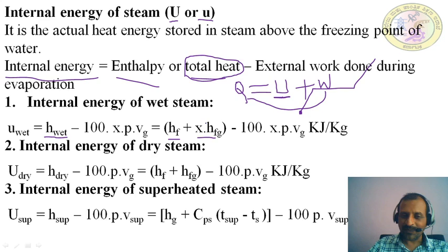And constant volume lines. There are some constant volume lines also shown here. And next is constant pressure lines. See here shown P 50 bar, P 10 bar, then 5 bar, then 1 bar, then 0.1 bar, right? So these are all the constant pressures shown here. Then next similarly there are isothermal lines, isentropic lines, throttling lines, right? But in this drawing only 3 lines are shown because the other 3 lines are out of your syllabus. So only 3 lines are important. Those 3 lines are shown in the drawing.